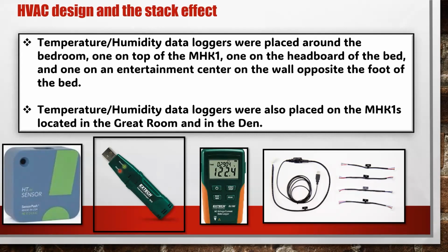Which is really the vast majority of houses for a multi-head system: 1,000, 1,200 square feet, 3-4 heads would be ideal. And these things scare me. I don't want to put them in at all. They're just overproductive. So we've got to get a little more creative and educate ourselves on what's really driving these complaints. We have learned most of it's due to oversizing, drastically oversized, not even doing heat loss calcs. Not every two houses are the same. Some houses are extremely tight and some are extremely leaky.